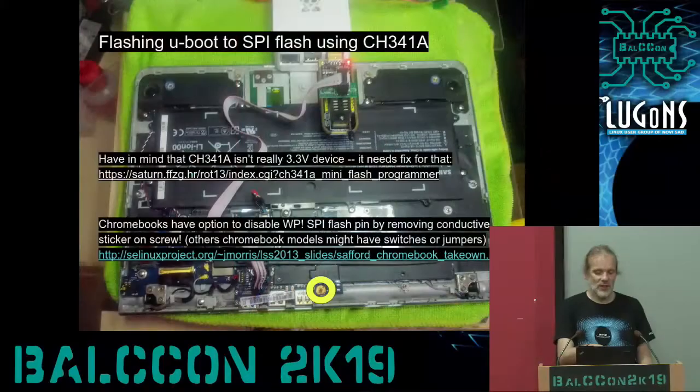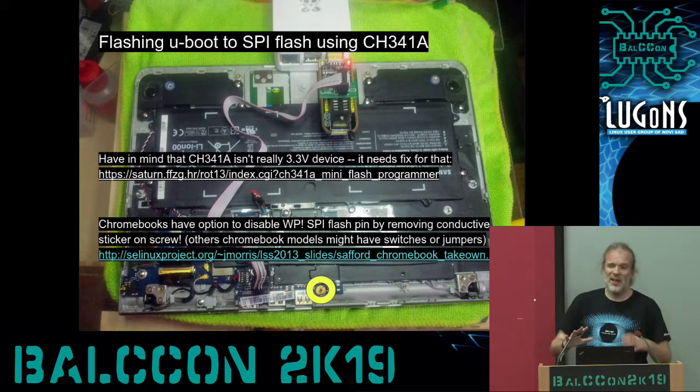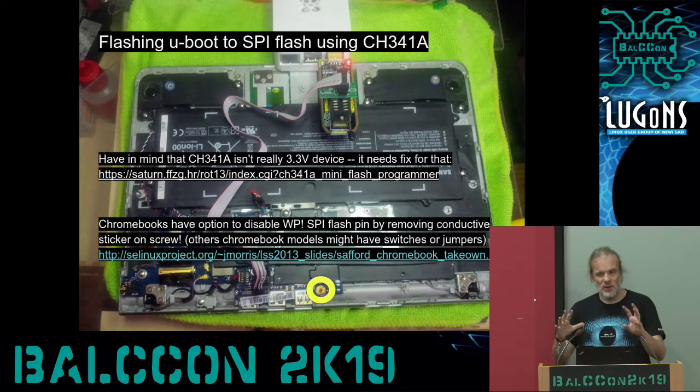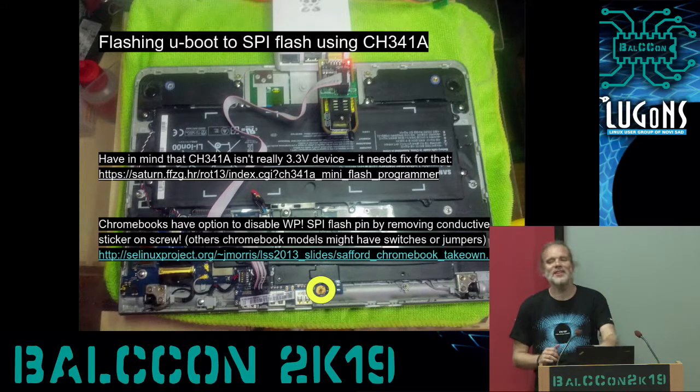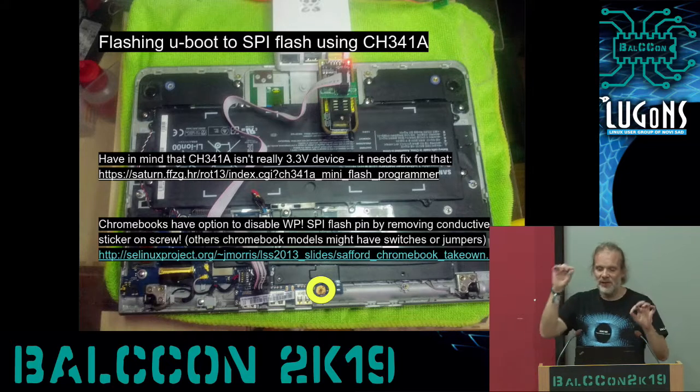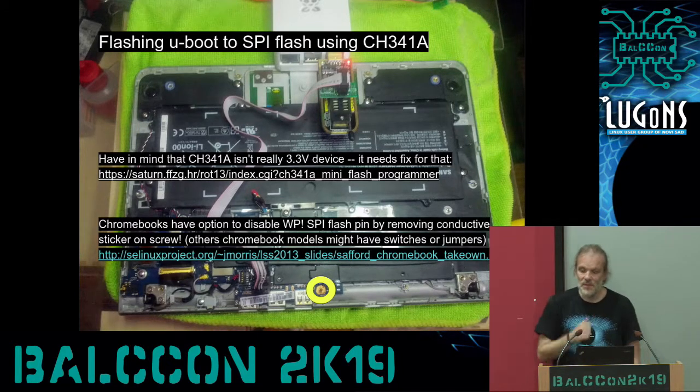On this slide, since I'm using a Chinese SPI flash adapter, I have to warn you that this flash adapter actually isn't 3.3 volts, it's actually 4.9 volts, and it will work with 3.3 volt flash, but if you really want it to be at 3.3 volts, just look at this link. It's a simple matter of lifting one pin and connecting the wire to the correct place.